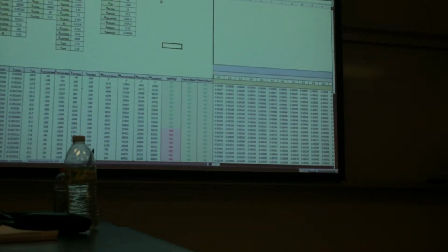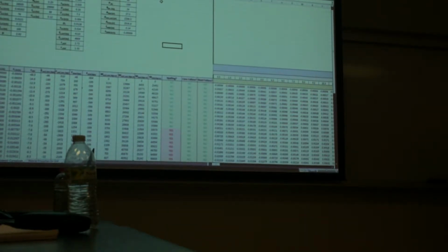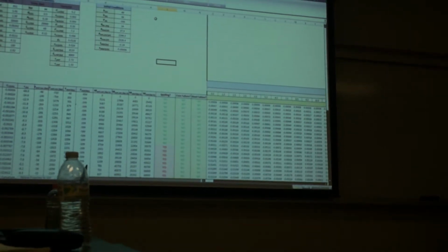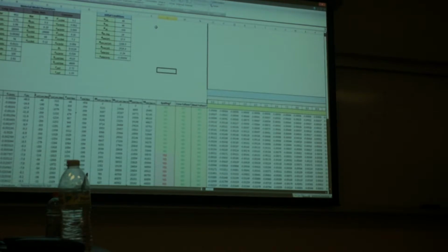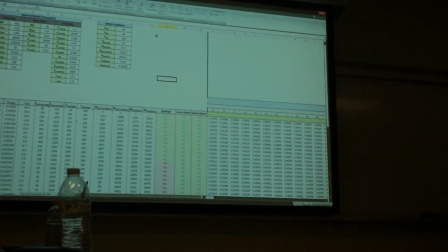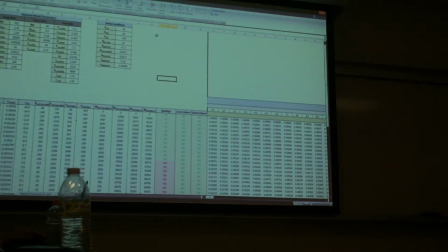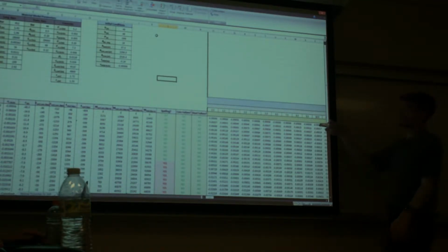So it's not too important, like you may say, well, it doesn't really matter for this monotonic analysis. When you do, let's say, cyclic analysis, you always look at the previous step of curvature for your strain states. So when you're doing, let's say, full dynamic analysis with actual earthquakes, you can't ignore that first step when you have initial strains there. Because as your analysis goes, it's going to keep looking at the step before it for strains. So this is for getting the initial strains in your cross-section.